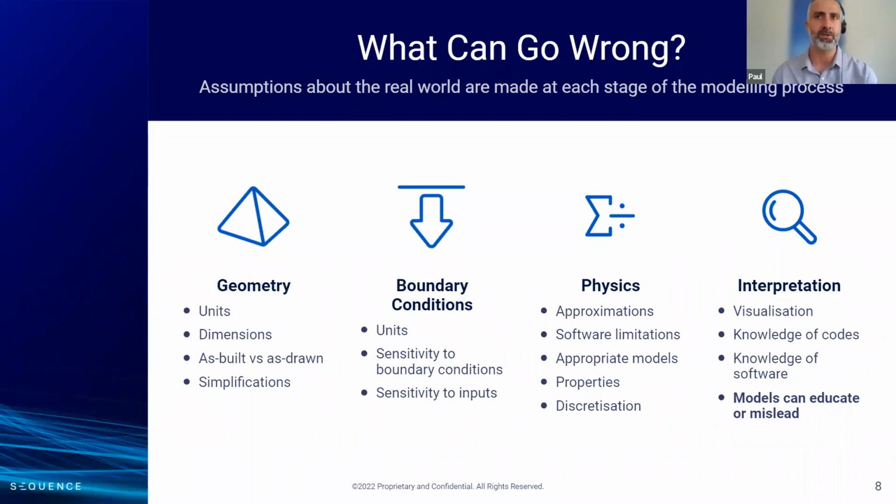Another classic example is assuming that air is constant density. That's probably fine if you're looking at flows where there's not large thermal gradients in a space, but when thermal gradients and buoyancy effects become important, that assumption could make your model meaningless. So the default values, the default physics, will often not lead you to the right result.